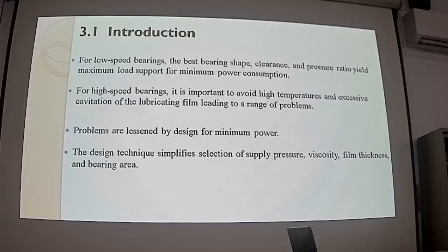Okay. This is for the low speed bearing. And for high speed bearing, here we call it the hydrostatic bearing or aerostatic bearing, it is important to avoid high temperatures and excessive cavitation of the lubricating film, leading to a range of problems. Cavitation is a special terminology for the thin film bearing.